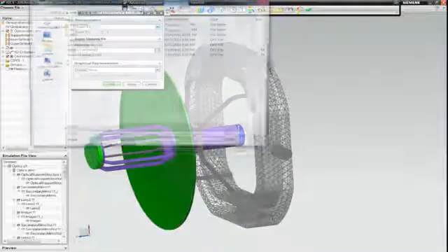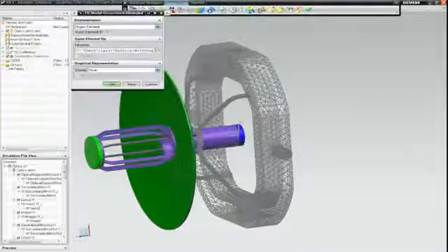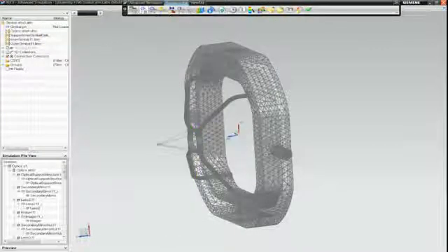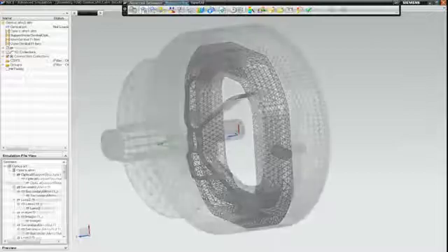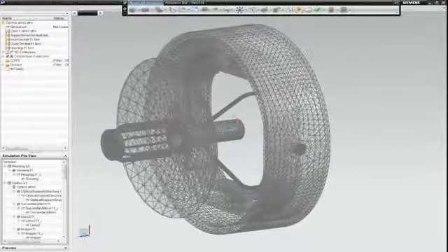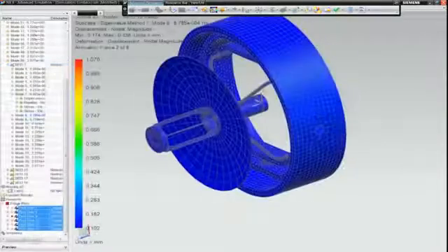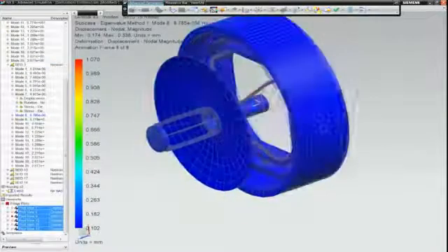Including superelements reduces the degrees of freedom for the complete system, which results in solver efficiency gains that can lead to quicker turnaround times. Another benefit of reducing components to superelements is the ability to share sensitive data with external partners without disclosing the shape or geometry of the component.